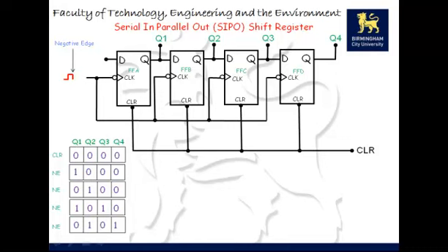What's the application of this particular shift register? Well, on this particular one, it's used for serial to parallel interfacing. One particular example could be on the output of a microcontroller. You might have a serial in, parallel out shift register, and this allows you to connect many peripherals to the output of the shift register. There may not be that many port pins available on the microcontroller, so it allows you to expand the I/O using shift registers.